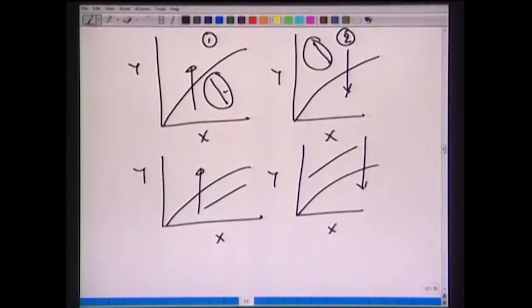We have drawn the operating curves and equilibrium curves, and we should also be able to mark all the slopes of minus kx over ky to obtain the interfacial concentrations at any location in the contactors, co-current or counter current.